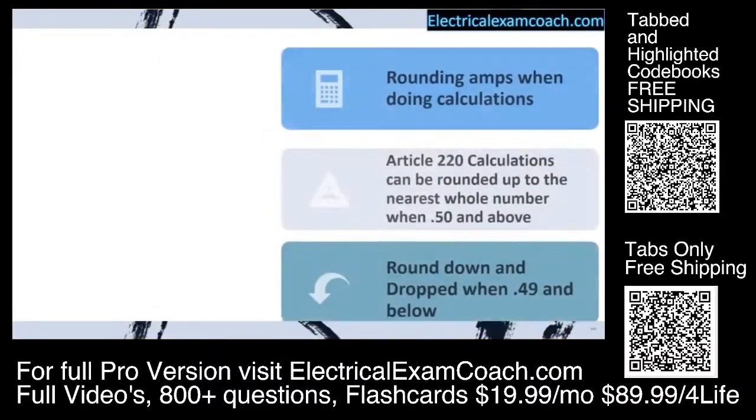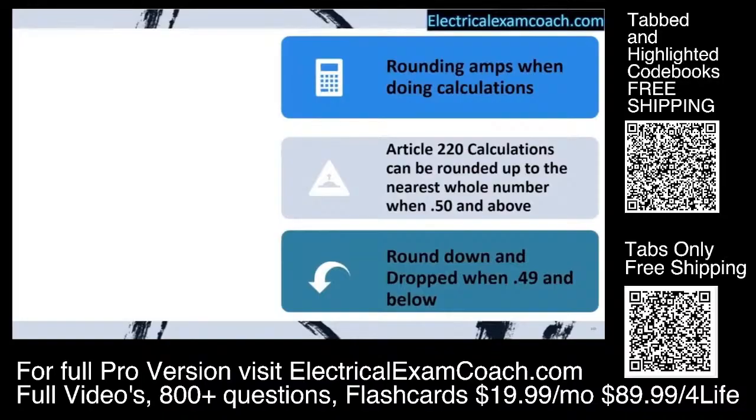In Article 220 calculations, we're going to be able to round up or down. We're going to round up to the nearest whole number when it's 0.50 and above, and we're going to round down and drop it when it's 0.49 or below. I want to let you know, though, that we're only going to do it one time at the end of the calculation. You're not going to be rounding up and down in between each piece, or you'll definitely end up with the wrong answer.